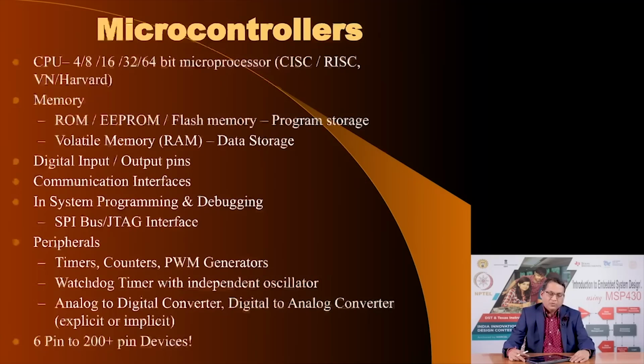offer. So, all microcontrollers are, as we have seen, nothing but a complete computer on a single chip, and therefore the CPU part of the microcontroller would be able to handle a certain amount of data bits at a time, and that is the bit handling capacity of that device. And it can range from 4 bits or 8 bits or 16 up to 64, maybe even more.